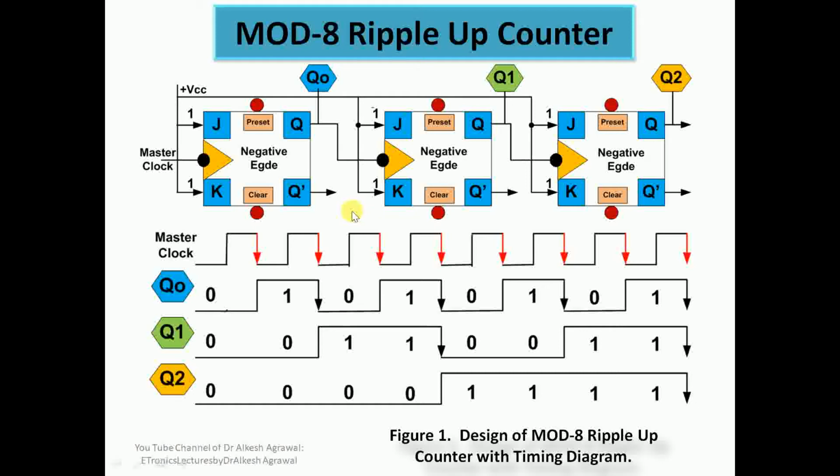and frequency divider circuits. So, here is one of the configurations in which we have three stages of JK flip-flop which are working in toggle condition. The negative edge triggered clock is used to activate a particular flip-flop. The stage to which we directly give the master clock is the LSB stage. So Q0 is the LSB bit and Q2 is the MSB bit. Q1 is the middle bit.